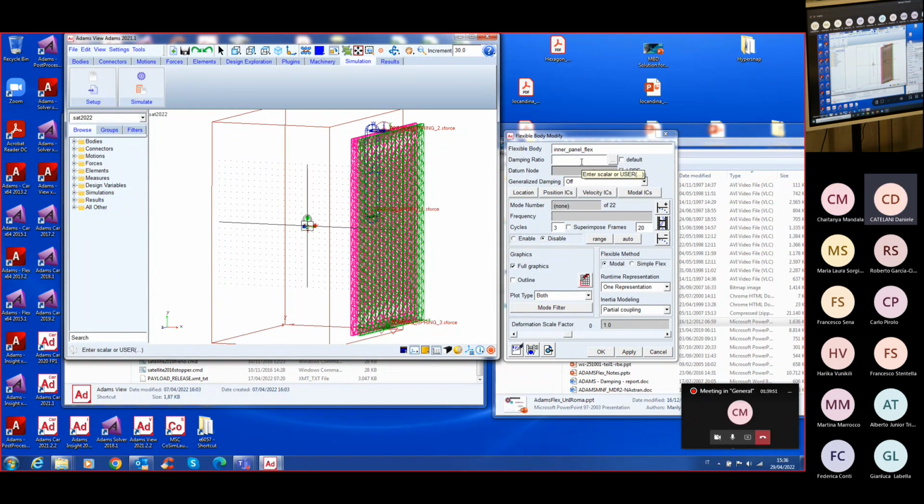If you want to change the content of the material, you need to use another technique of analysis called co-simulation, in which Adams and Marc or Adams and Nastran are working together. It is a little bit complex in terms of modelization and requires more computational effort because you have two solvers working in parallel.